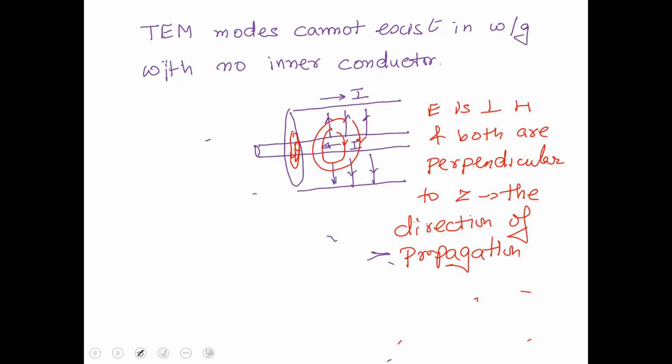So you took this transmission line and you analyzed it with an equivalent circuit model. You basically said, I have an electric field confined within the two conductors that acts like a capacitance per unit length. And I have a magnetic field looping around between two conductors, and that's as if I have an inductance per unit length.